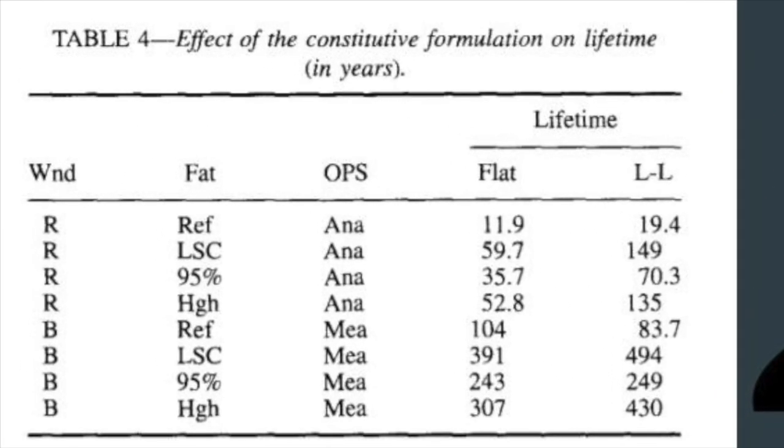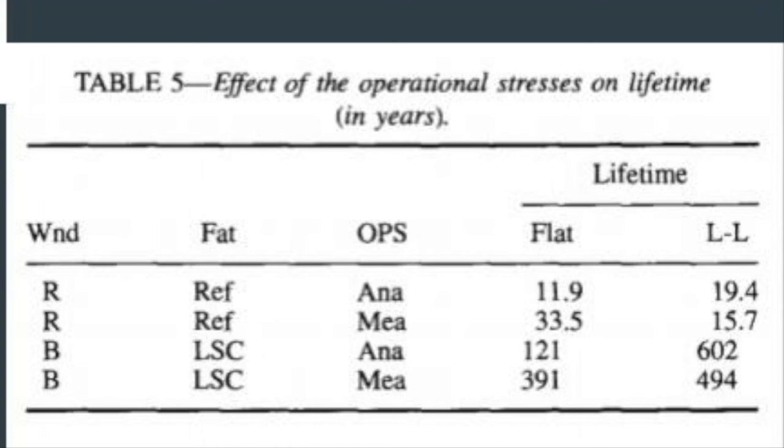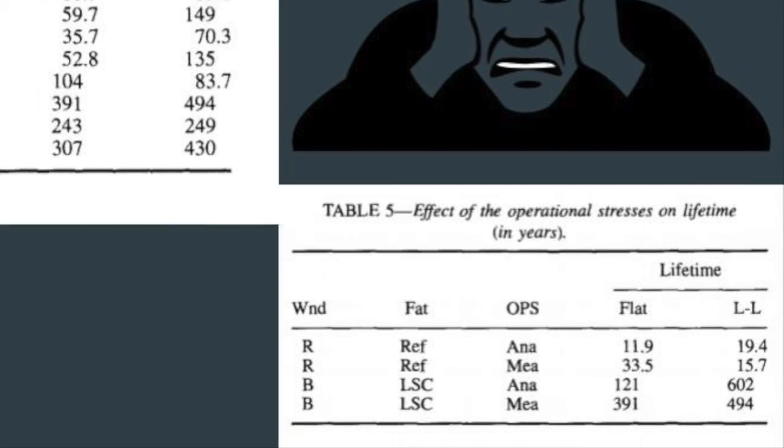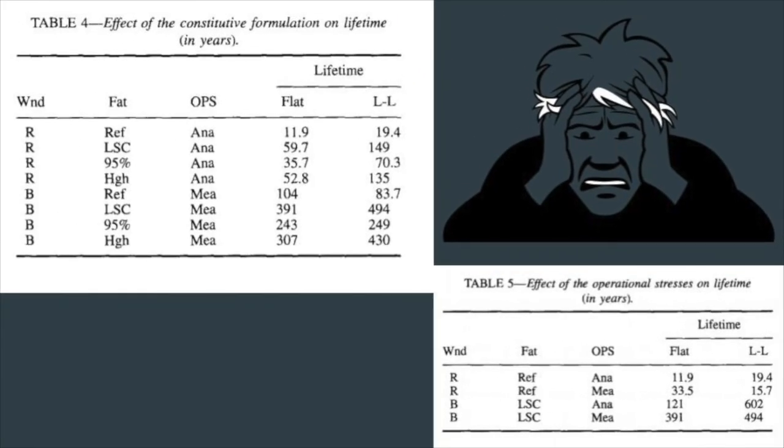Here, Table 4 incorporates 4 different SN estimates, and Table 5 compares the analytical RMS stress with the measured RMS stress. Overall, comparing the estimates between cases, they seem to vary in magnitude by around a factor of 10. It would be smart to take the more conservative estimates if using this data, but it just goes to show how difficult it is to predict the lifetime of a wind turbine.